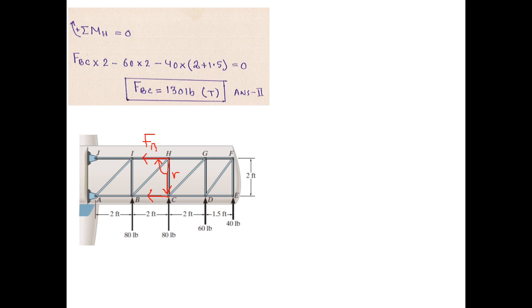So we have just taken this force FBC momentarily and joined it with the tail of R. So this step we have done in our minds only, right? Just to make sure that we are using the right rotational sense for this force in our equation of moment. So indeed it's a clockwise moment, as you can see.